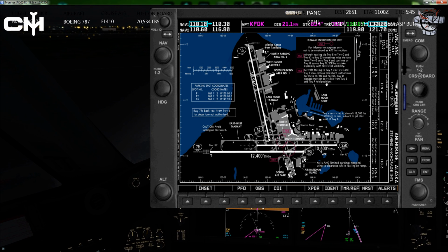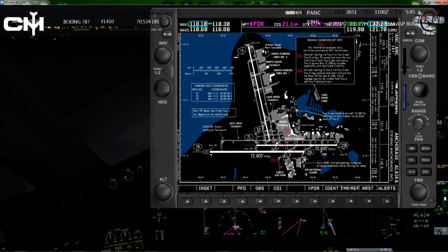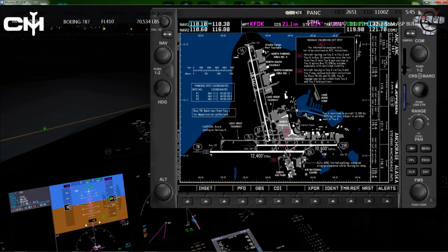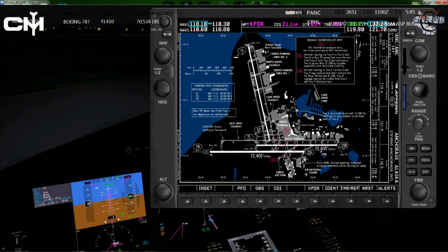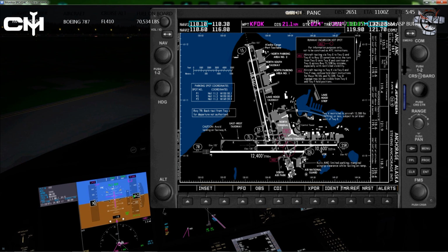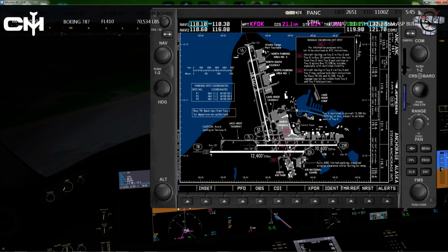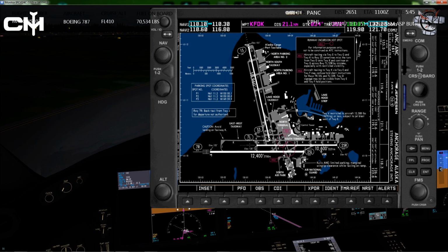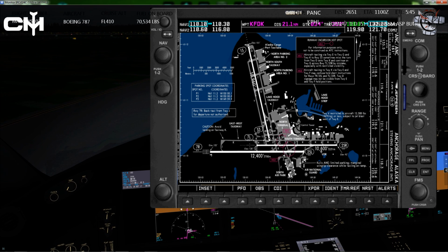These are runway incursion hotspots. So hotspot number 1 is pretty close to us. Aircraft taxiing via taxiway E, Echo, which is the taxiway that runs right here, actually. This little crossway here from runway 25 left, to taxiway G and taxiway K, so this is G over here and this is K right here, and then to runway 33.